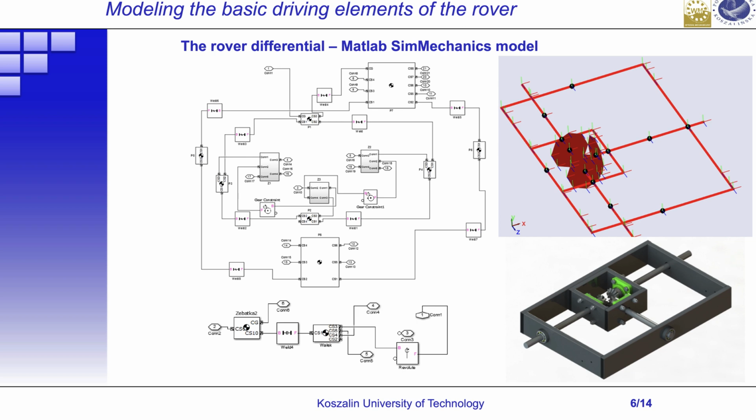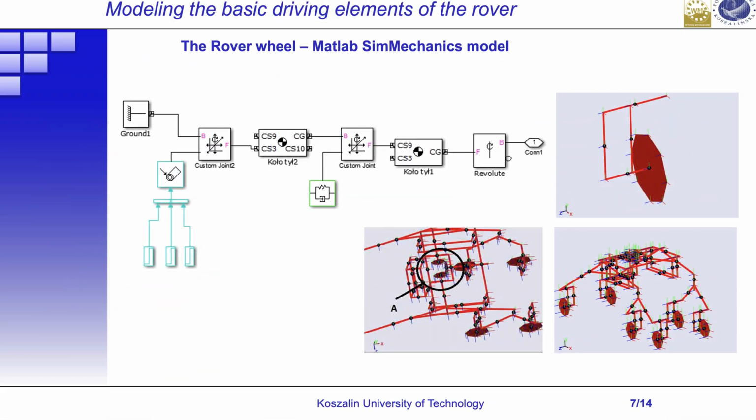The mechanism itself is located in subassemblies Z1, Z2, and Z3. These are 3 gears mounted on 35 mm long shafts, connected by gear constraint blocks used to define the relationship between the wheels. Finally, elements P5, P6, P7, and P8 were used to make the outer casing to which the battery holders will be attached. The final component completed was a modified rocker bogie suspension which included the legs, cylinders used to adjust ground clearance, wheel mounts, and the wheels themselves.